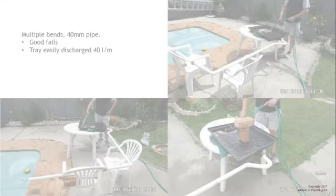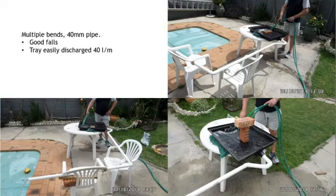So here's another configuration. This is now 40 millimeter pipe. So we've dropped down in size to 40 mil pipe. Don't worry about those bricks. It's just to keep the tray in place. All manner of bends. Look at the funny bends that I put up there, sort of backing up upon itself, and 90-degree bends and funny, and it easily discharged 40 liters a minute because it had a fall. Every part of it had a fall, straight from the get-go, boom, out, round that funny S bend, round a 90-degree bend, no problem. 40 mil pipe, because it had a fall.